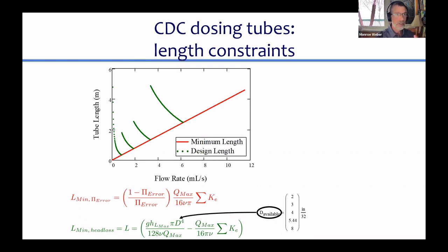And you should always be wondering, why was 20 centimeters chosen as the, I don't know, perfect design for AguaClara plants? If we go to more head loss through our linear flow orifice meter and through our dosing system, that ends up meaning that the head loss through the entire plant increases, because all the water goes through the linear flow orifice meter.